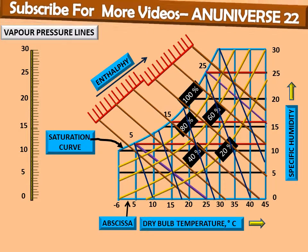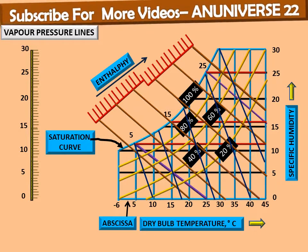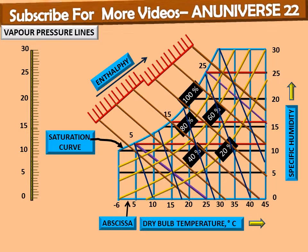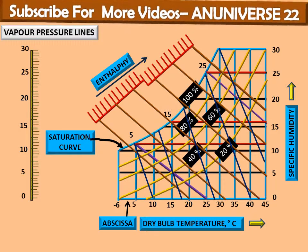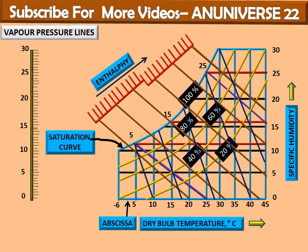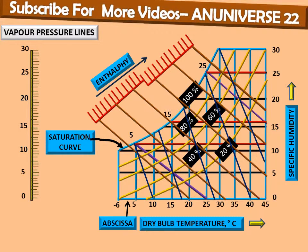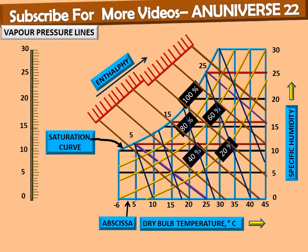On the psychrometry chart the various lines indicate various psychrometry terms showing the condition of air. If dry bulb or wet bulb temperature are known, the relative humidity can be determined. If dry bulb temperature and relative humidity are known, the wet bulb temperature can be found. If wet bulb temperature and relative humidity are known, the dry bulb temperature can be read from the chart. And if wet bulb temperature and dry bulb temperature are known, the dew point temperature can be found. And if wet bulb and relative humidity are known, dew point can be read from the chart. If dry bulb and relative humidity are known, dew point can be found.